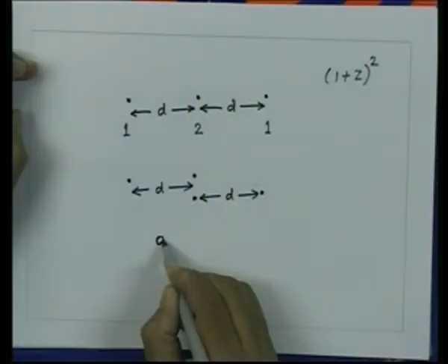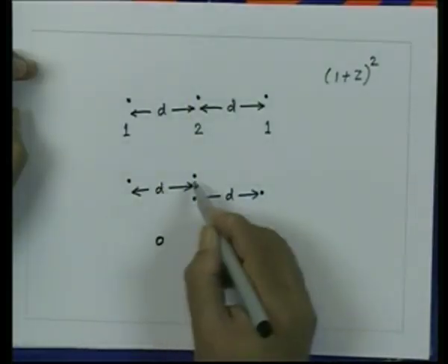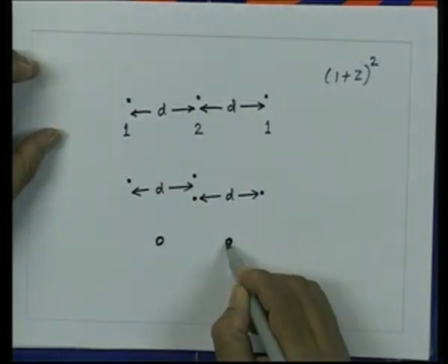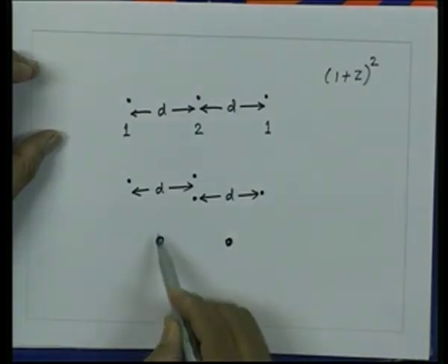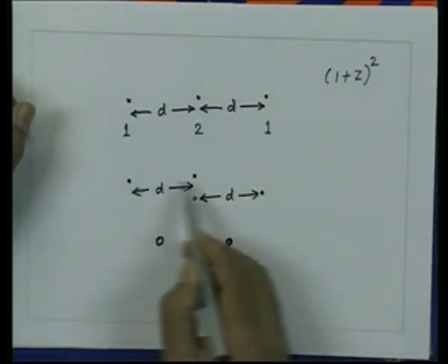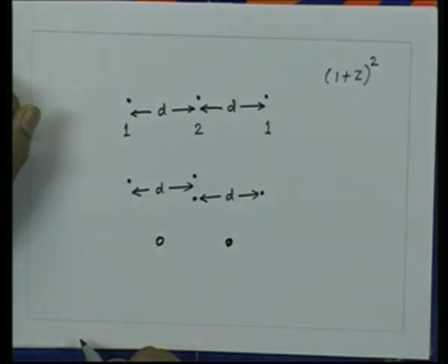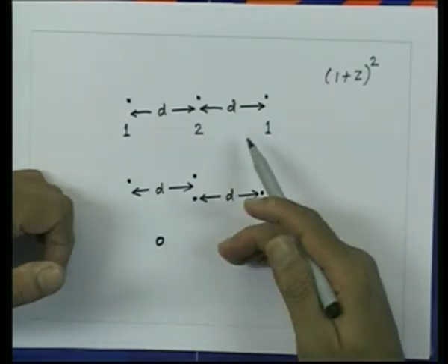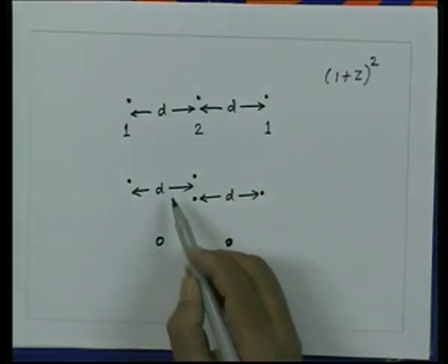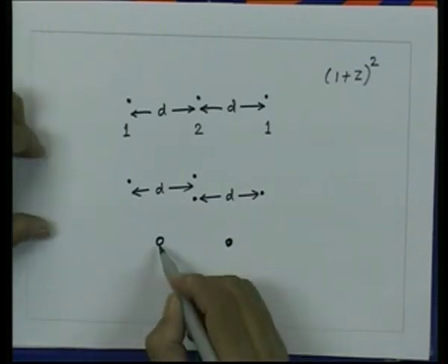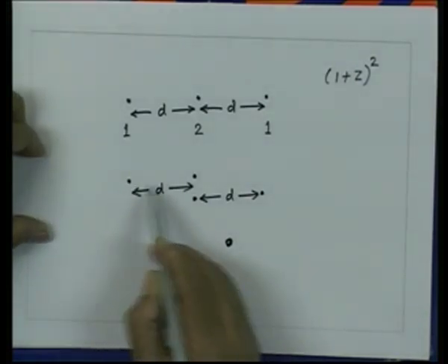So, these two combined together, now I can call another element which is effectively located at the center of these 2. But now this element is not isotropic, because this element is representing the combination of these 2 elements. So, initially these elements are isotropic radiators, but if I think of this as a combination of 2 arrays and I say this array is equivalent to this radiating element, then this one has a radiation pattern which is the radiation pattern of these 2 element array.